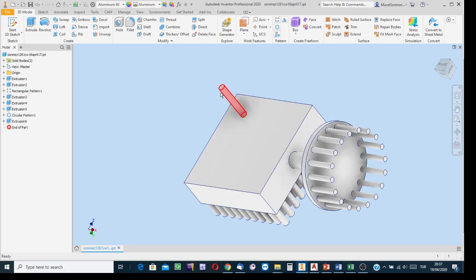Since in this example I said that this distribution is about the center of the surface, the axis is to pass through the center. I already marked the center of the surface, so I just turn on the visibility of the sketch. In that sketch, I am sure I already marked that point. I used it for locating the base of this extension, using the radial coordinate.